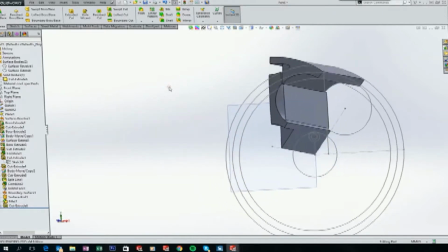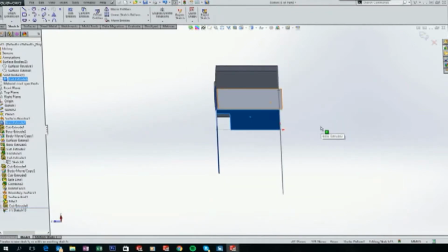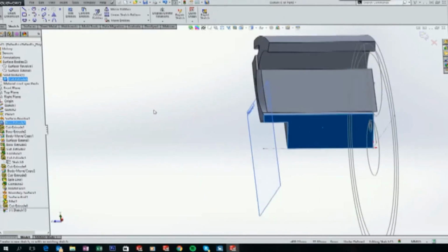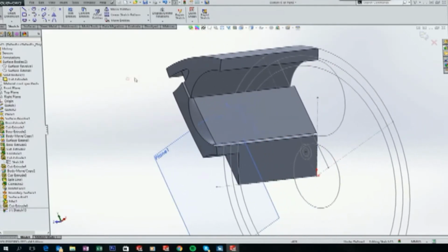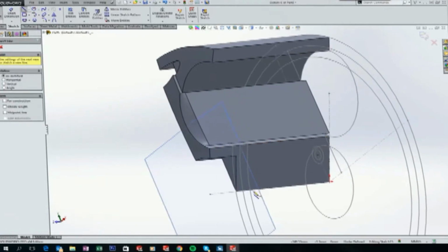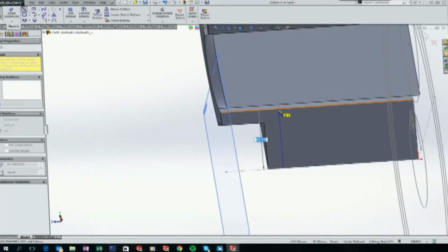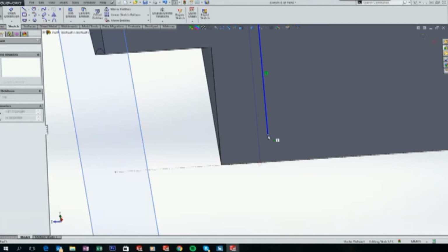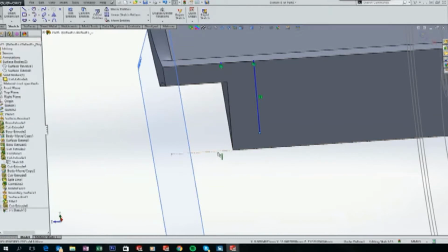Now click on this face and start a new sketch. You can press Ctrl 8 to view it normal too. Like this. You can simply just view it from this way that I'm doing here. Now choose your line tool. Sketch a line down from this edge up to this edge. And finish here and double click. Make sure you can drag this point a little up and Control click the center line and make it coincident.